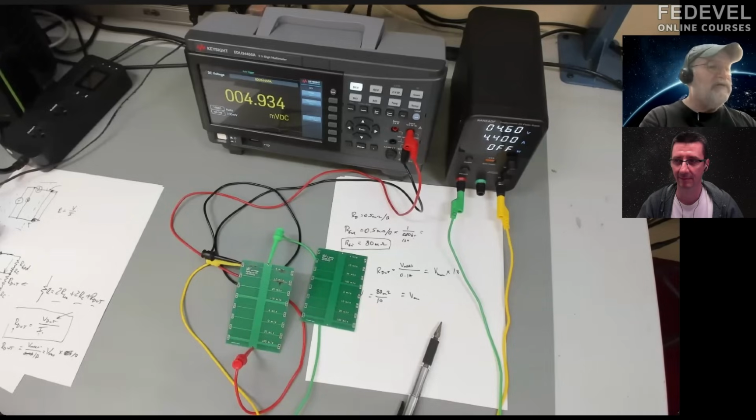That's a very reasonable, safe margined value for max current through a 20 mil wide line. So I always say, if you're designing a board where the worst case current you're going to see on any power rail is 3 amps, then there's no reason not to use 20 mil wide traces to carry the current for distributing power.